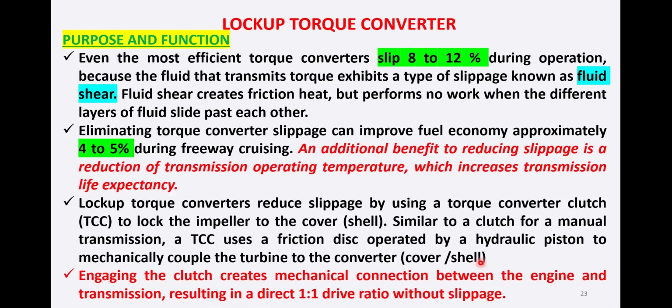Now a few words regarding one subtopic of the torque converter, that is the lockup torque converter. Now, what is a lockup torque converter? The purpose and function: even the most efficient torque converter slips 8 to 10% during operation.